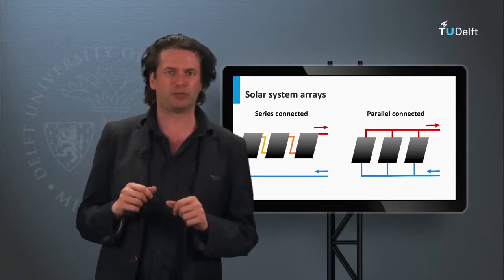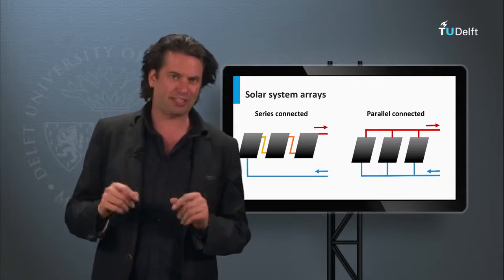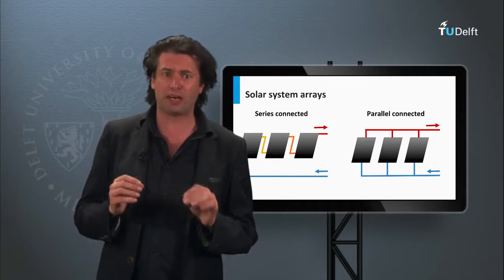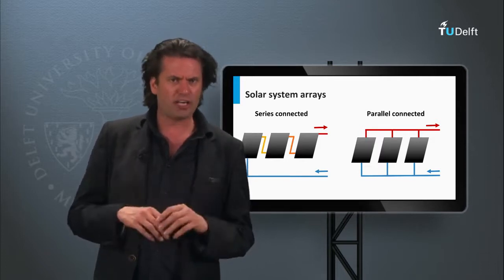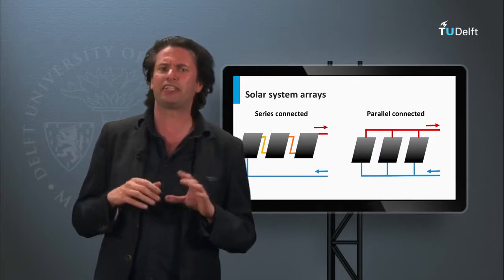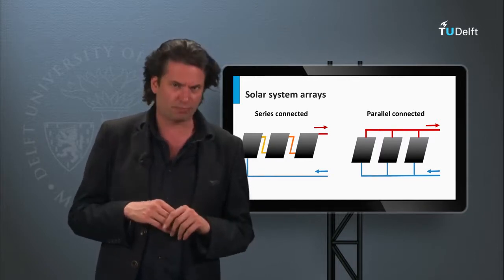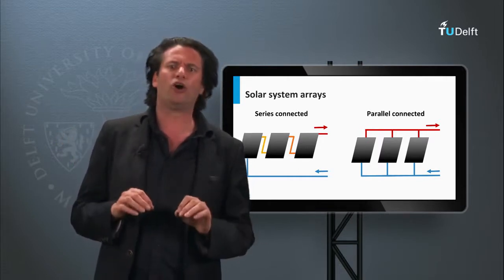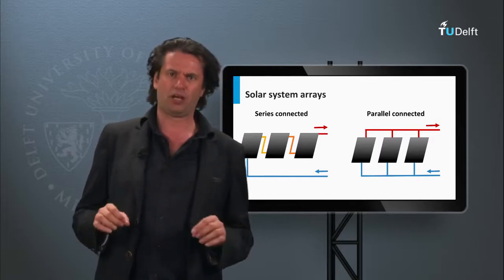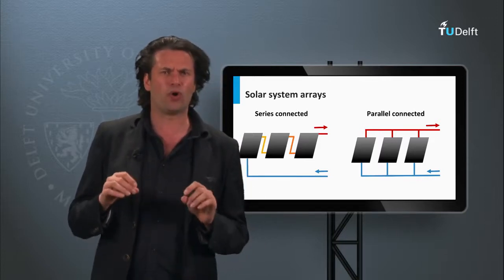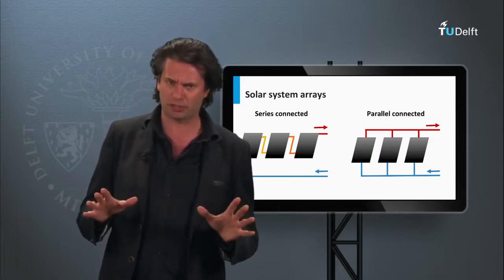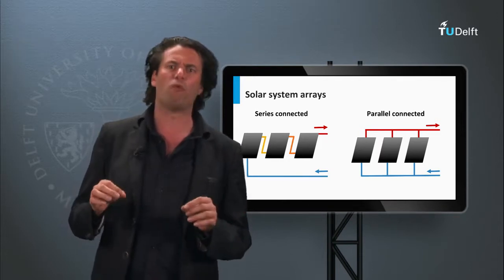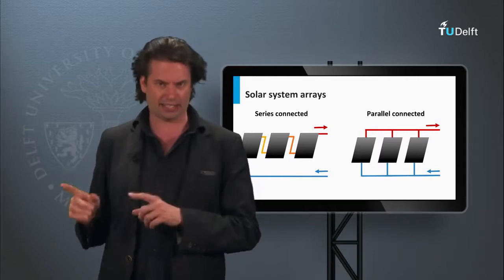Most commercial and industrial systems require a large number of collectors to satisfy the heating demand. Therefore, a combination of collectors in series and in parallel should be created. Parallel flow is more frequent because it's inherently balanced and minimizes the pressure drop. In any case, the choice of series or parallel arrangement depends ultimately on the temperature required for the system. Connecting collectors in parallel means that all collectors have as input the same temperature, whereas if the series connection is used, the outlet temperature from one collector is the input of the next.